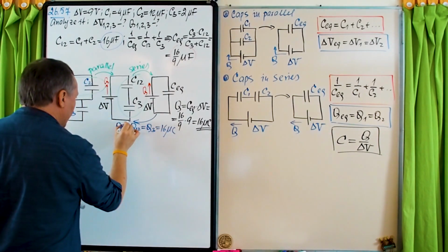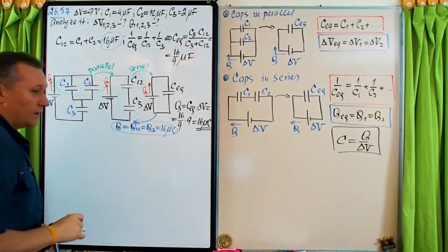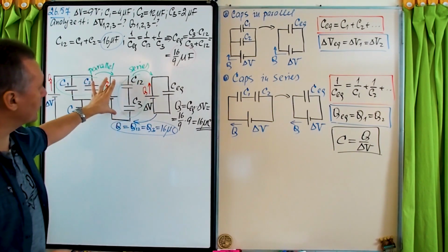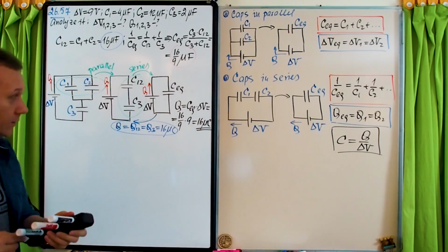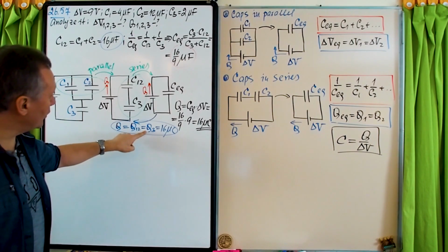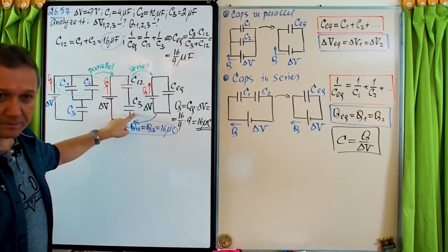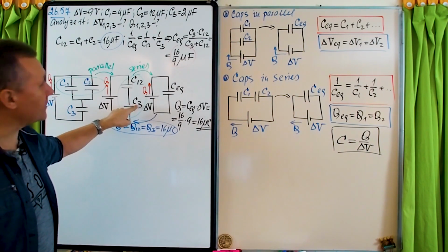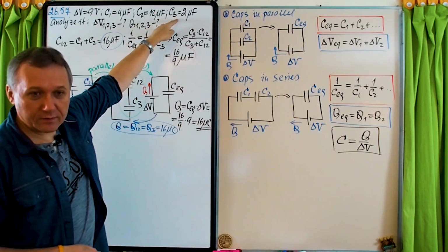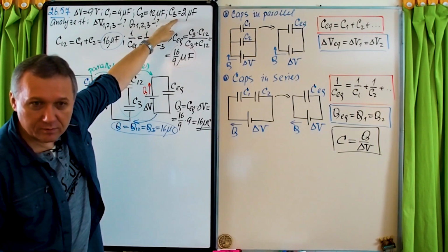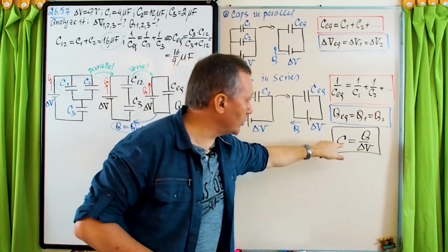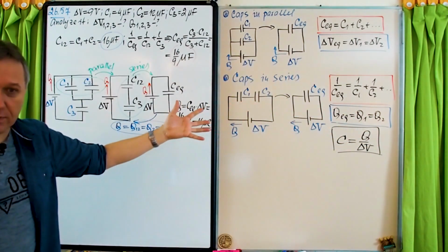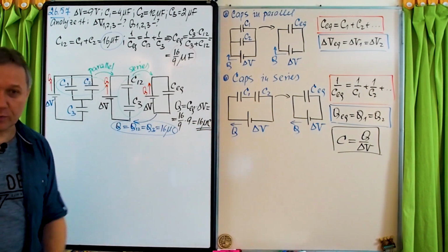So basically, that's what I call a bridge, which we use in order to move from this circuit back to that one. And now look, now we know the charge in the capacitor C3. If you know the charge in the capacitor and you know the value of the capacitor, 2 microfarads, can you find the potential difference? Piece of cake. Again, the formula: you know charge, you know capacitance, you can find potential difference. Again, you see every time we use that formula.